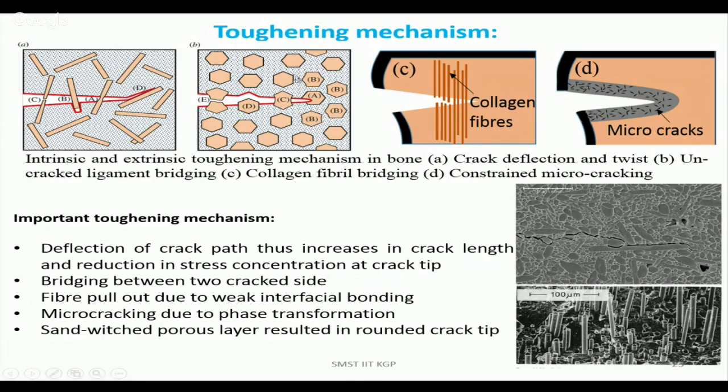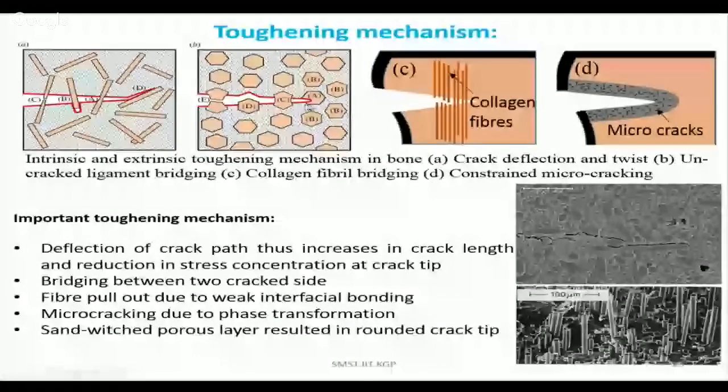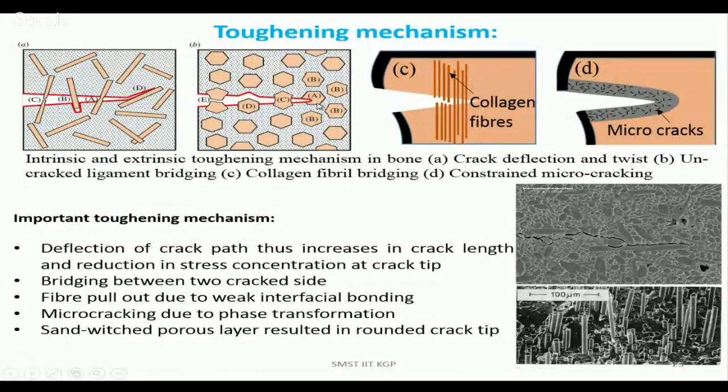Similarly, in the case of platelets, you can see some of the platelets break down. Some platelets are still acting like a bridge, and in some platelets you can see the crack propagating through. Even some platelets can have crack deflection because of a weak interface between the platelet and the matrix.